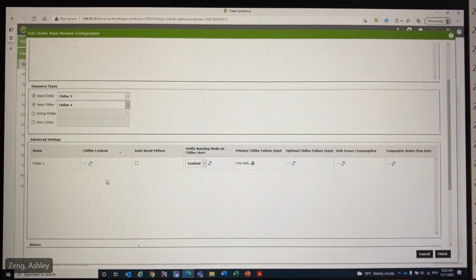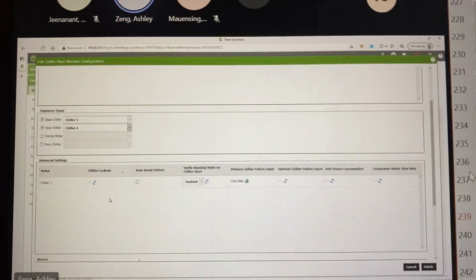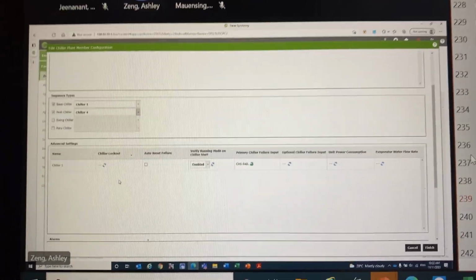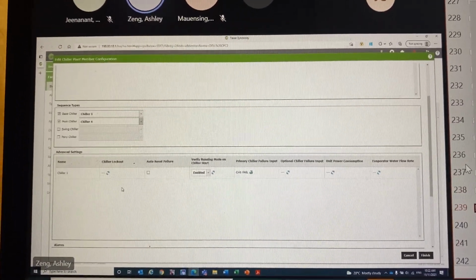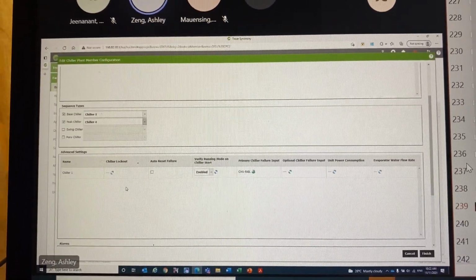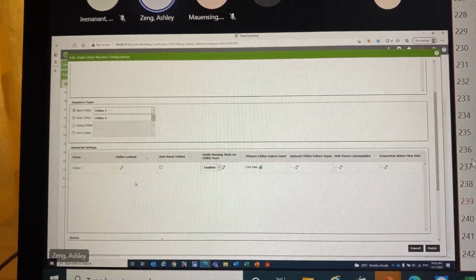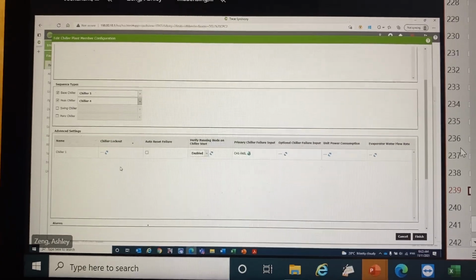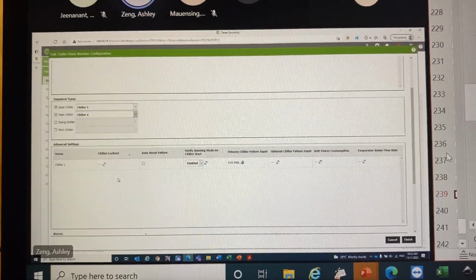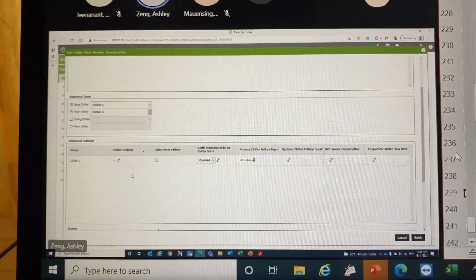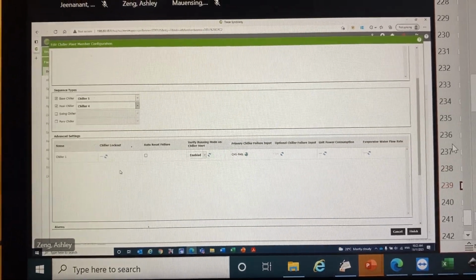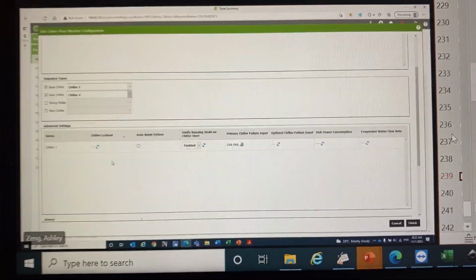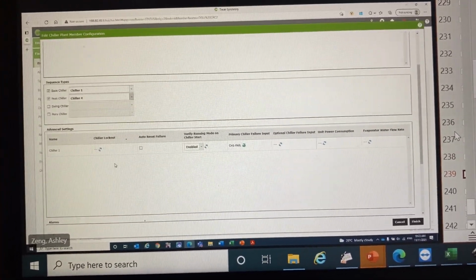I think the syntax is usually either auto or BMS, then you have local or manual, and there's also a state called off. As long as the selector is not within auto or BMS mode, you also want to mark that chiller as a lockout. Then you can tie those points in as well. It's all going to be scripted in your TGP tool itself.